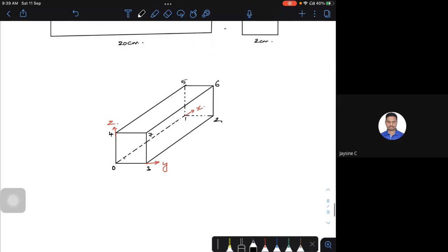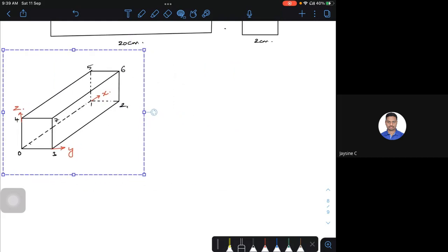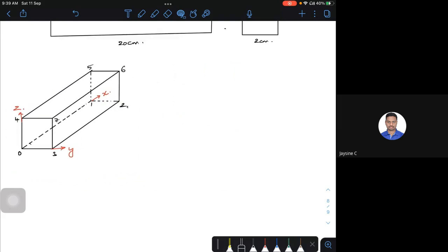So if I want to define these vertices, what should I do? Let me write that: vertices. Then the same thing we are going to type in the blockMeshDict file. Whatever rule I am trying to tell, this rule is applied for almost all the things. What are vertices? Vertices means the points. I need to define the coordinates x, y, and z. Now, what corresponds to 0? For 0, it is 0, comma 0, comma 0.